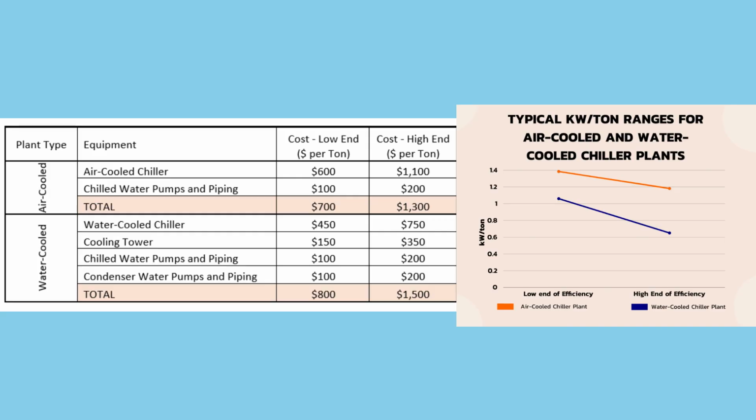Modern software tools like Trane Trace, System Analyzer, EnergyPlus, and eQuest allow engineers to model these trade-offs using actual weather data, utility rates, and hourly load profiles. Always evaluate life cycle cost, not just first cost, especially when pursuing LEED certification or compliance with ASHRAE 90.1.